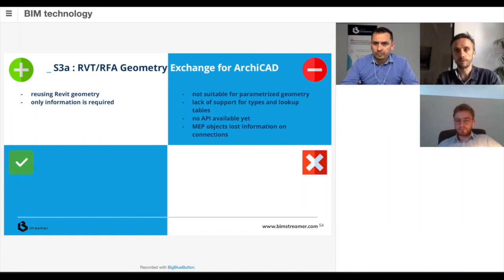As you may have noticed, the interface of this add-on is very simple. It allows us to import only three types of elements: basic objects, windows, and doors. And there is no way to pass any other options that are in the Revit family. And as you mentioned, there's no API, so we cannot transform it in a more automated way.